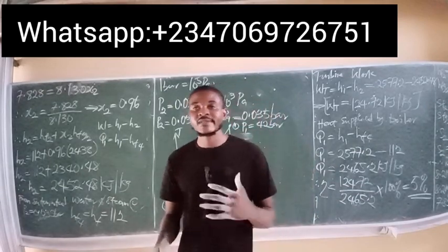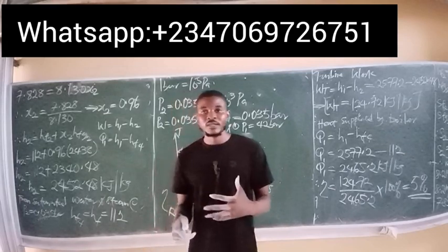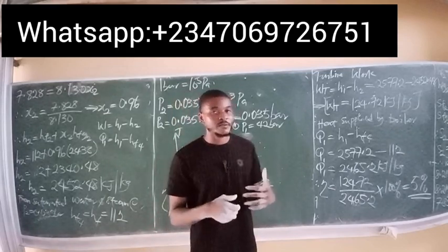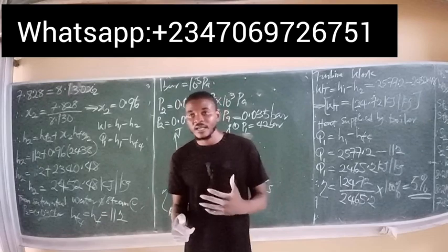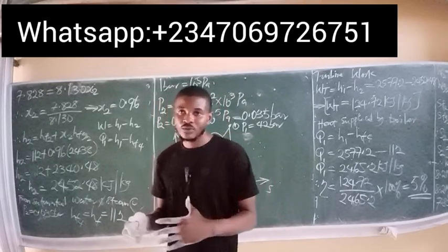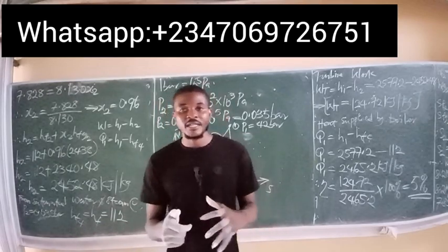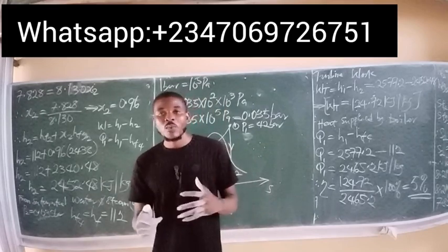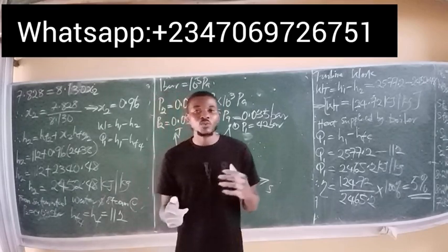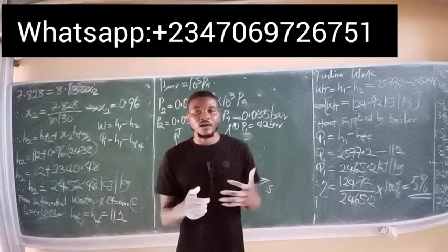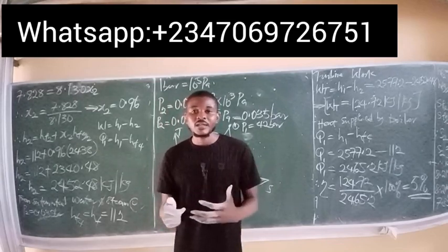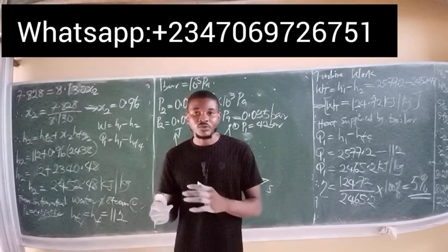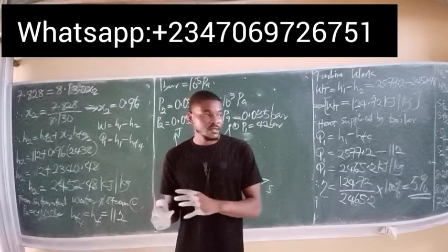All right, guys. So I will see you in the next video with more questions on Rankine cycles. So please take note, in this question, we weren't given temperature, so which means we have to work with the given pressures in the saturated conditions. But in subsequent questions, we'll encounter temperature, which actually means we'll have to look for the values of the enthalpy at the corresponding temperatures and pressures using the superheated steam table.